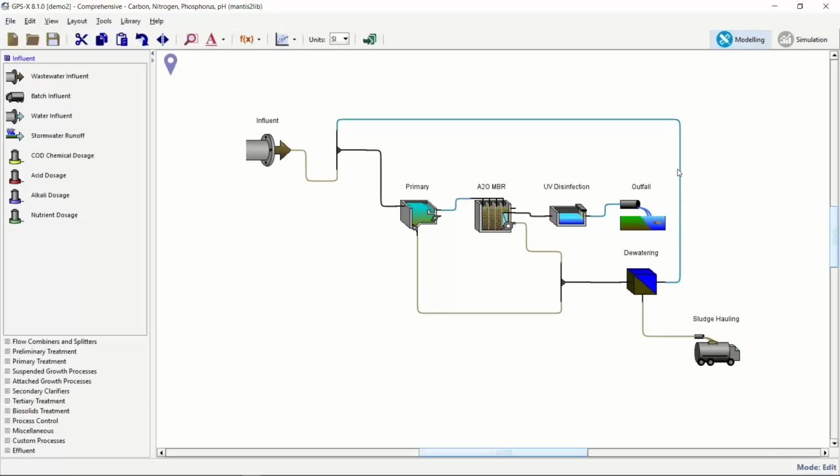And we got into this long discussion about the way that this person had set it up. And he was a little bit confused about why he wasn't really seeing really great A2O type BioP removal in the MBR. The orthophosphorus was being removed, but not as low as he had expected. And then anytime he tried to optimize some other part, like to maybe change up the denitrification a little bit, it seemed to make the BioP worse. So what we did was we played around with his model, and I always remember this was when I was a bit more at the beginning of my career than where I am now.